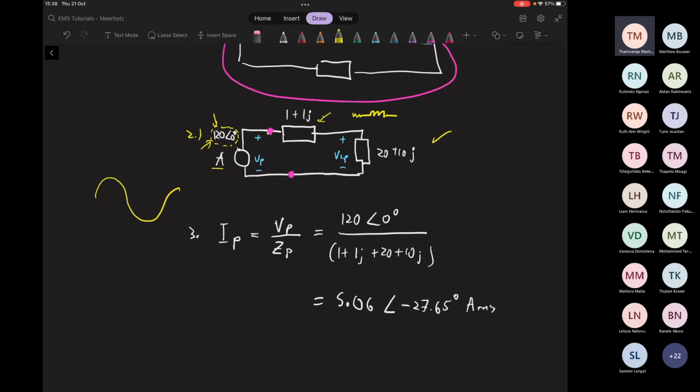So two inductive loads here. Remember, inductors follow this formula. I'm just giving a perspective of what's actually happening. V is equal to L di dt. So we're differentiating a current, or you could say you're integrating a voltage. And remember, when you differentiate or integrate a sine wave, you get a kind of shifted sine wave with a magnitude change.